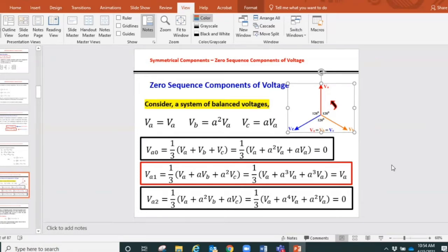Do you understand that this diagram is a positive sequence phasor diagram, and it is showing that VA is the first one to achieve any point on the sine wave, and then VB will come after that, VC will come after that? Do you understand that? If you don't, just let me know, I can explain it.